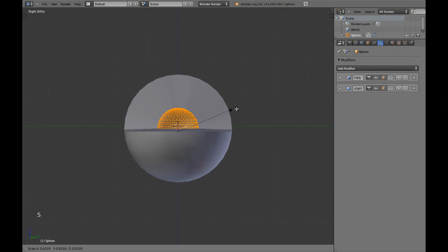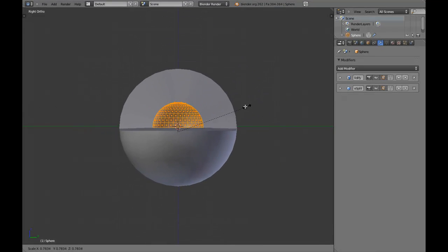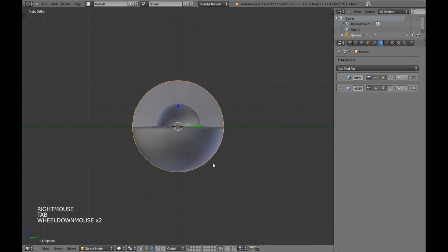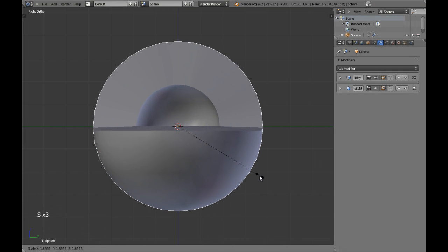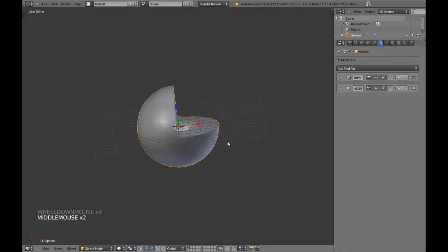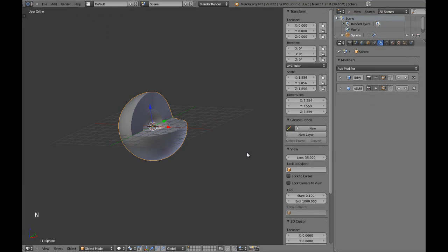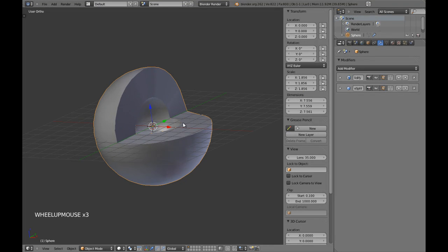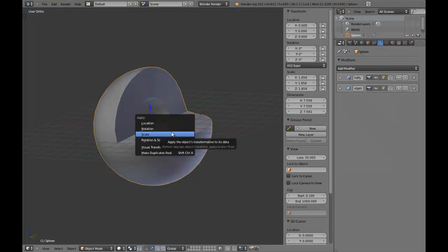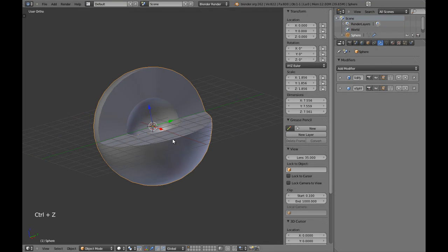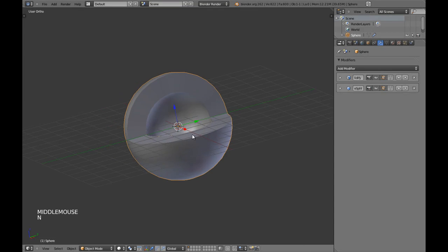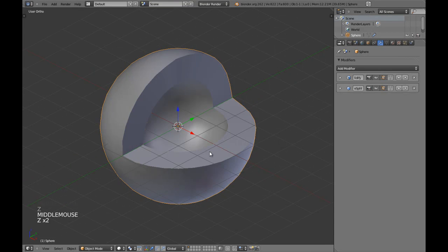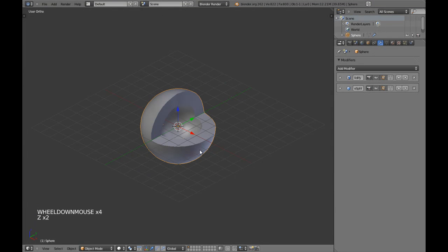If you do it in edit mode, you will get differences. I hope you can see the difference. For example, let's say I will scale this out of edit mode, okay? And you will see here that we have a different scale now. So this is not 1, 1, 1 as default. If I apply rotation scale, you will see how Solidify is changing. So you will have to be careful with that, just in case something is looking not the way you want.